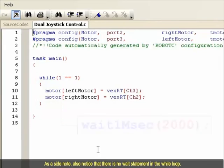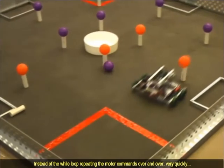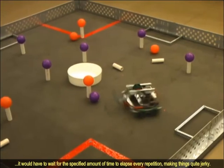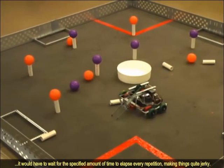As a side note, also notice that there is no wait statement in the while loop. In fact, adding a wait statement would only make our control over the robot less responsive. Instead of the while loop repeating the motor commands over and over very quickly, it would have to wait for the specified amount of time to elapse every repetition, making things quite jerky.